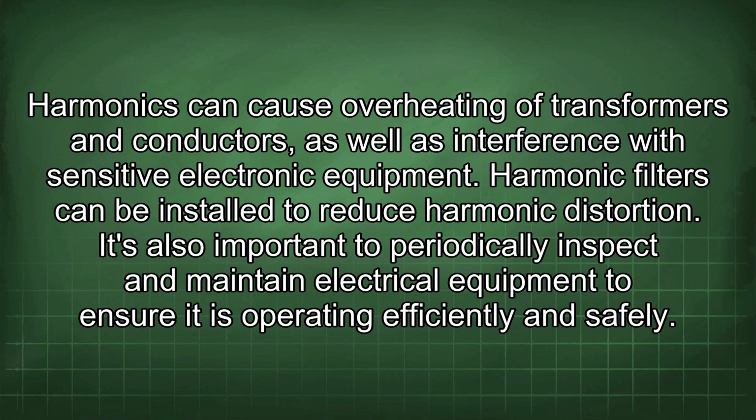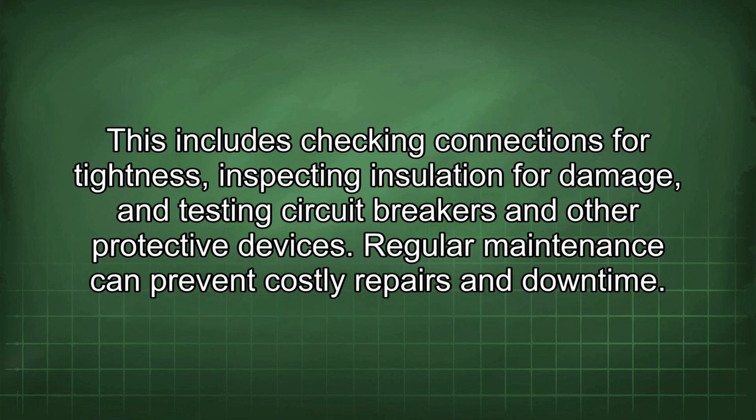It's also important to periodically inspect and maintain electrical equipment to ensure it is operating efficiently and safely. This includes checking connections for tightness, inspecting insulation for damage, and testing circuit breakers and other protective devices. Regular maintenance can prevent costly repairs and downtime.